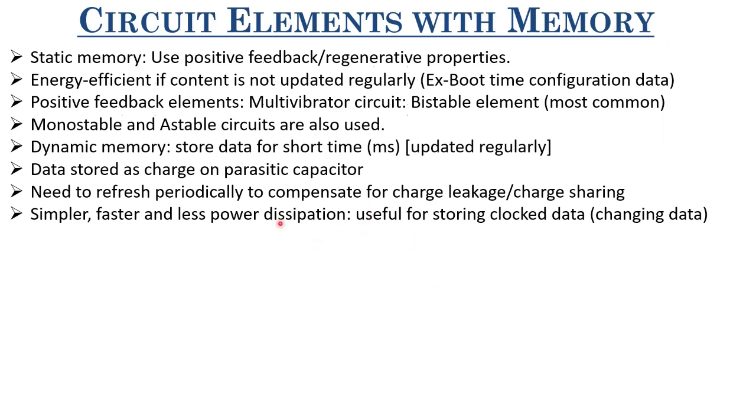So there's this problem. See, refresh actually adds to a lot of power dissipation here. But if you just consider the power dissipation of the individual dynamic cell or dynamic register, that is low. So here I would like to point that out. Refreshing it consumes a lot of energy. However, if you talk only about the dynamic register, standalone, its power dissipation is less. But if you talk about this refresh process, then that takes a lot of energy.